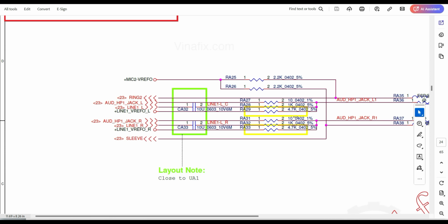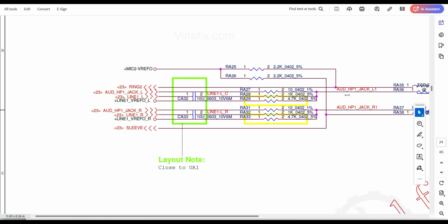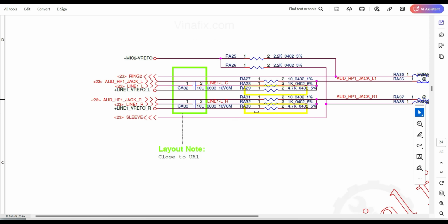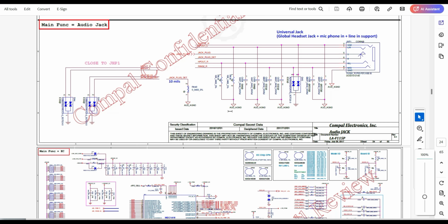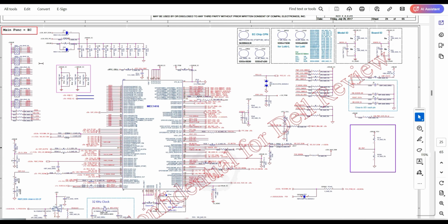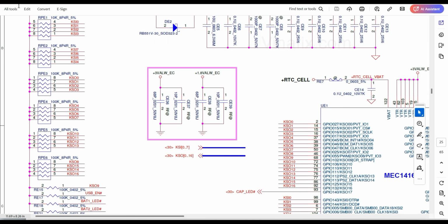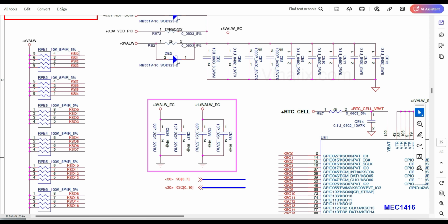Here the resistors are there. Here is the input; this signal will go through a 10 ohm resistor here. The output here has no resistor, only the input. Here is the output but no resistor. Here is the pull down, which is connected to the ground, the audio jack, and here the network resistor has been given. See, these 3 volts will become this one. It depends on the active component. Internally, if it is connected to the ground, then the complete circuit will happen and the same voltage goes to ground. In case it is an open condition, then the same voltage will go here.